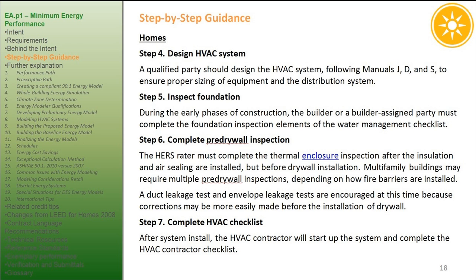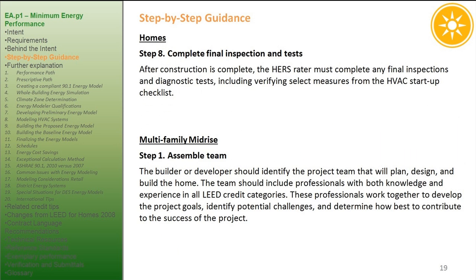Step 7. Complete HVAC checklist. After system install, the HVAC contractor will start up the system and complete the HVAC contractor checklist. Step 8. Complete final inspection and tests. After construction is complete, the HERS rater must complete any final inspections and diagnostic tests, including verifying select measures from the HVAC startup checklist.